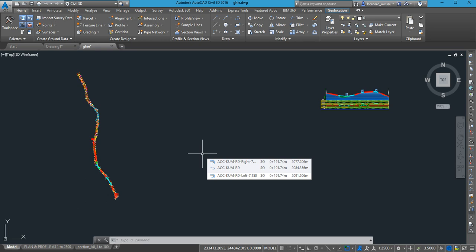Please, are we okay? So we are going to create our assembly, which we are going to use as our typical cross section. Remember yesterday we said that our lane width is 3.65. Then after the lane width, we have a shoulder of say 2.5. Then after the shoulder, maybe a drain or something. So that's what we are going to draw. Please, let's do it together.